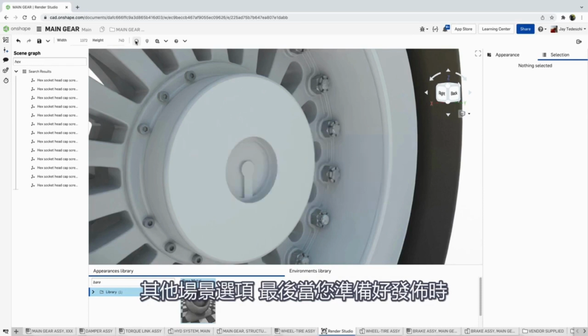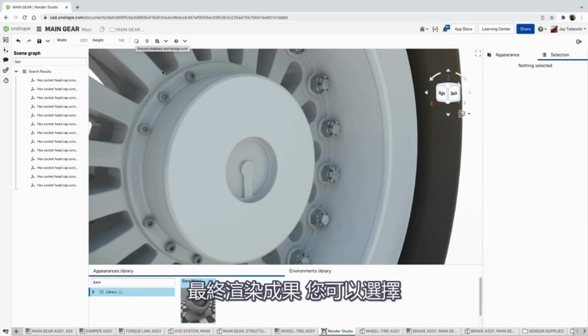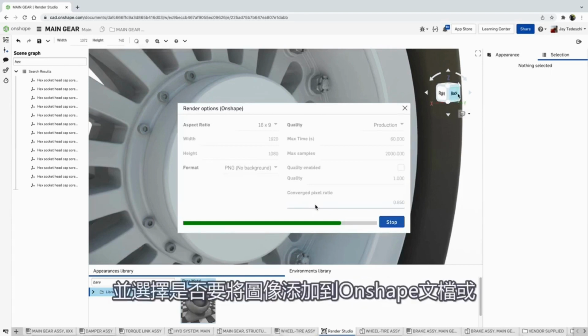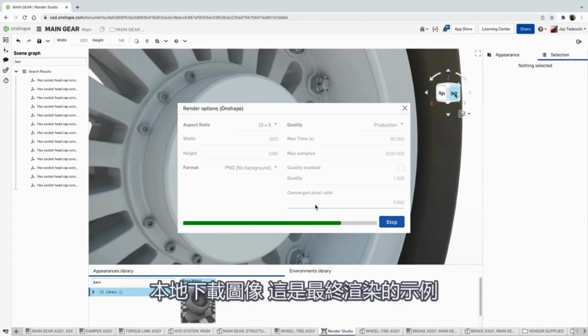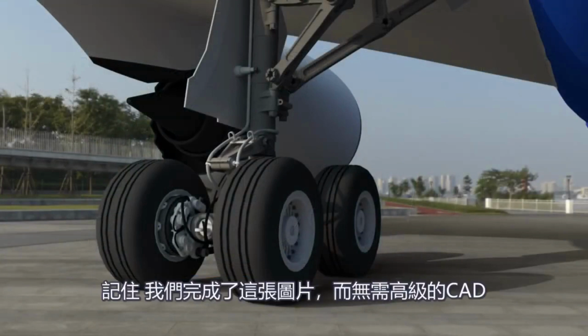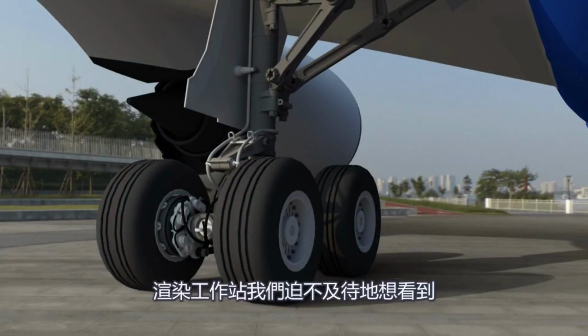Finally, when you are ready to publish the final rendering, you can choose to add the JPEG or PNG graphic with the correct resolution and rendering level, and choose whether you want to add the image to the Onshape document or download the image locally. And here is an example of the final render. Remember, we did all of this without needing an advanced CAD rendering workstation on our desktop.